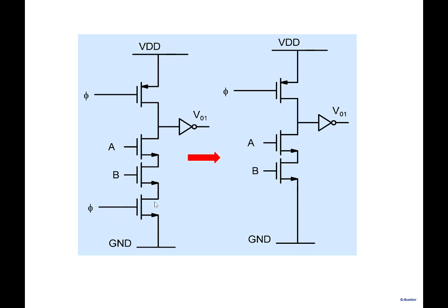So this particular transistor is removed to improve this. In many of these high-speed designs, this transistor goes by the name footer. It's like the foot of this particular gate here. So it's called a domino without the footer transistor. So without this particular one.